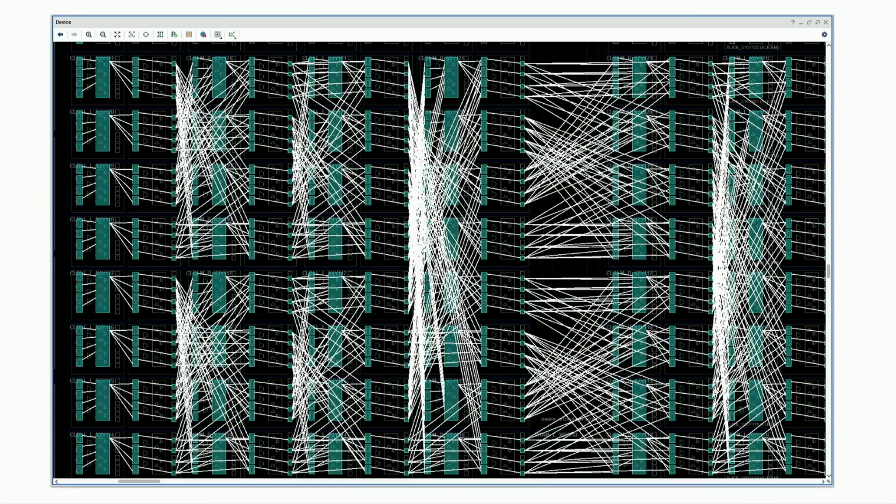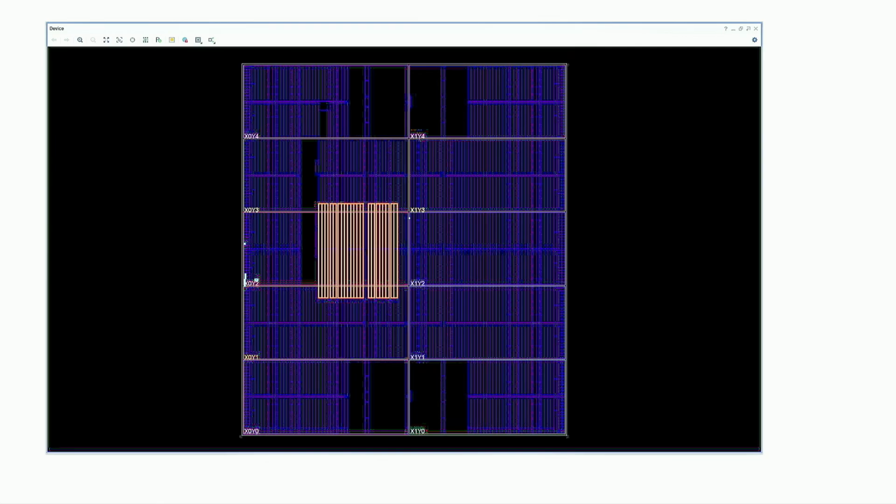And then when you give it to tools to place and route, for an 8 input sorter, this is the picture you get. And I think the butterfly pattern is clearly evident and looks similar to the original picture that I saw, which I think is quite beautiful and nice. From these simple algebraic descriptions with beside, below, par, etc., you've composed behavior. This thing will sort numbers when you put them in, and you get a nice compact implementation of the sorter on the FPGA.